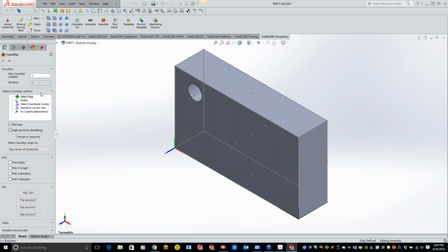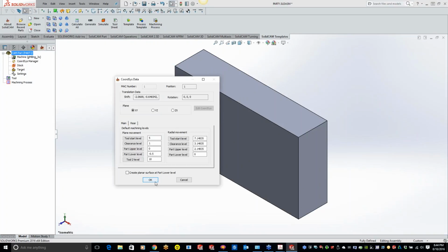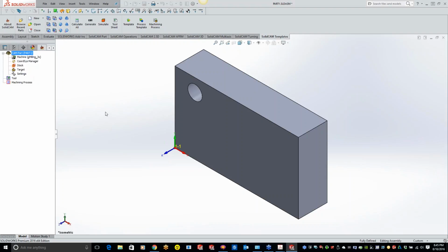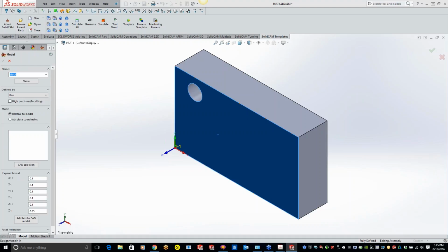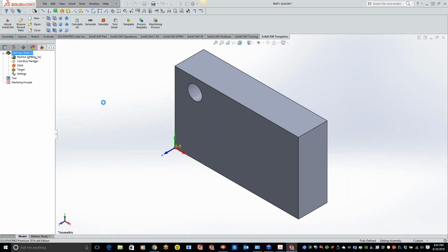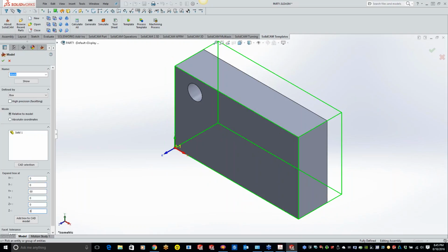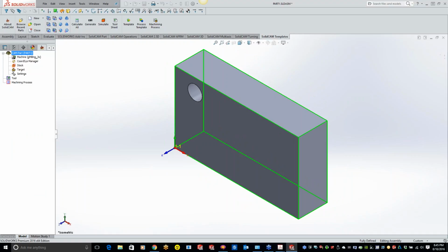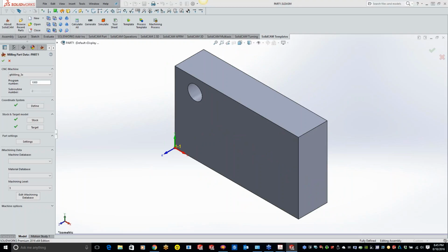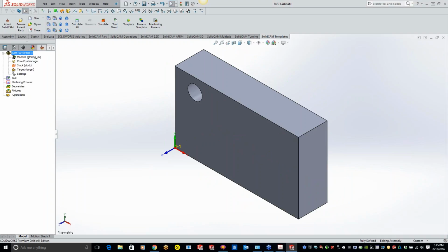What's interesting about this Laguna machine, Kevin, is it's got a controller on it, but please forgive me, Richard, it looks like the controller is fairly antiquated and may actually not support actual G cycles in terms of pecking, deep pecking, or chip breaking cycles. So that could be interesting.